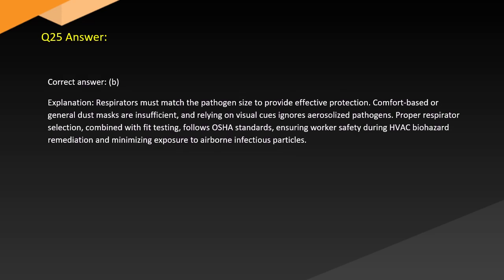Answer. Correct answer, B. Explanation. Respirators must match the pathogen size to provide effective protection. Comfort-based or general dust masks are insufficient, and relying on visual cues ignores aerosolized pathogens. Proper respirator selection combined with fit testing follows OSHA standards, ensuring worker safety during HVAC biohazard remediation and minimizing exposure to airborne infectious particles.